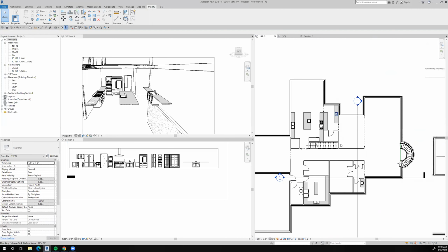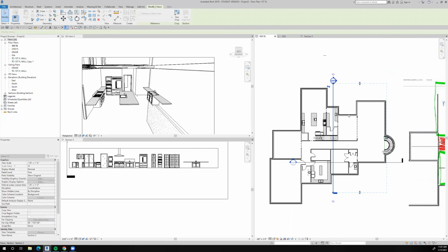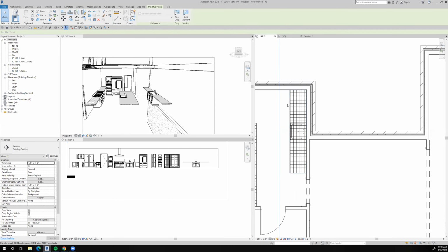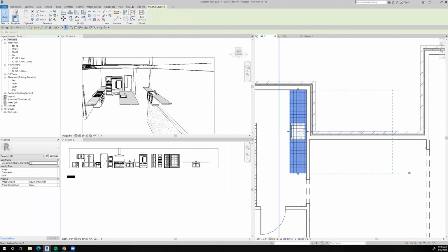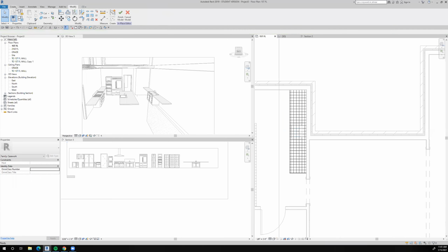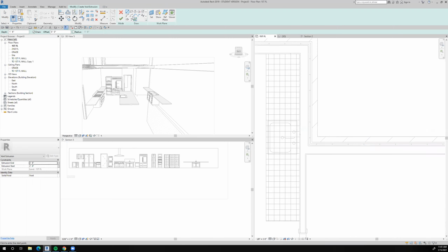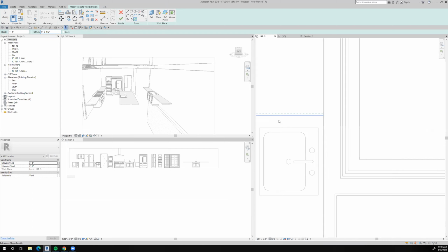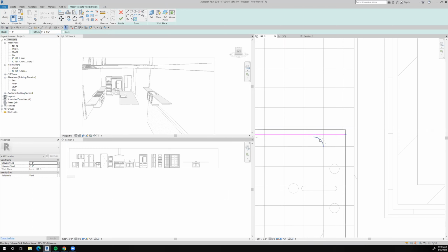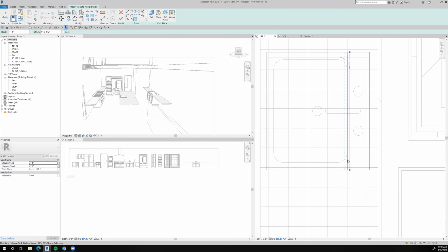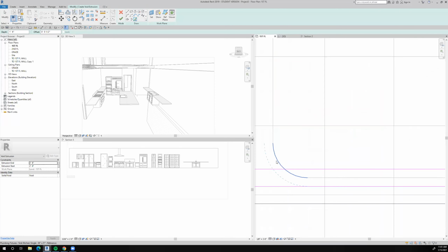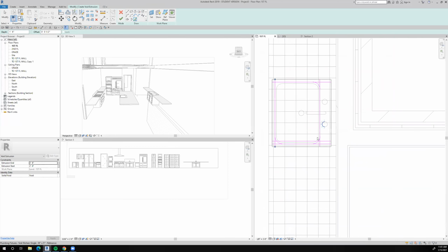Let's do that. This time I want to bring this section line over here to show you. Maybe I can explain it this time with the void extrusion. Edit in place. We're going to create a void extrusion. Now it's above and below. Okay. And again, we're going to have to use the pick lines and just offset 0.5 inches. We'll do the same thing again, all the way around. Again, I put it on the wrong side. Not a big deal, I can go back and delete that.